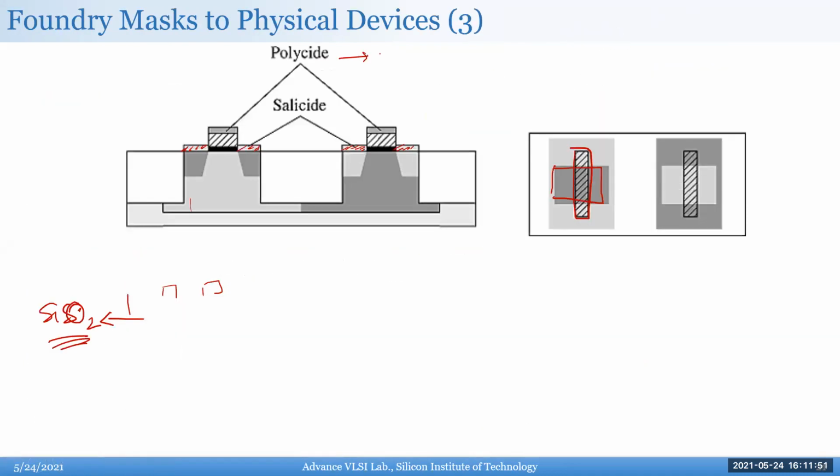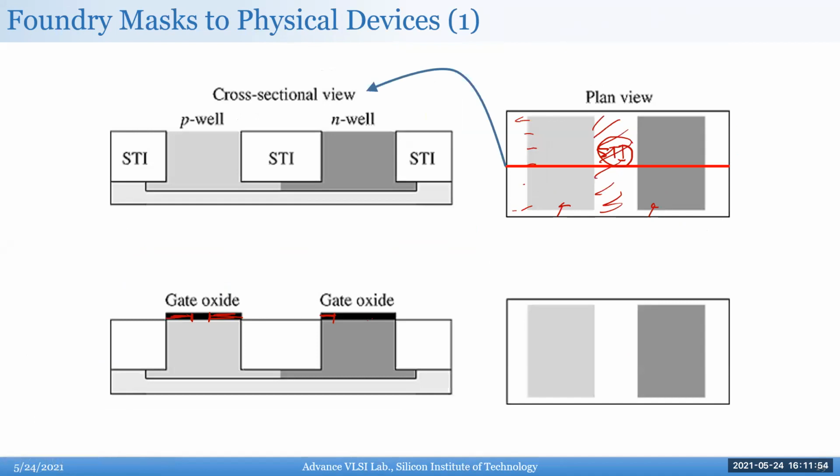A lot of you are still imagining this process as a PCB kind of process, where you take a few devices and connect them by wires, but you have to realize this is a monolithic stack process, right? This is a layer of stacks, and you go in the reverse direction. You see the stack going from top to bottom, and when you're fabricating, obviously you go in the reverse direction. It's like those reverse Polish calculators. If anyone has used one, it drives me nuts, but you put in the stack whatever you want in the order you want and it gets calculated, right? It's like your C programming stack. So you have to imagine it as a stack.